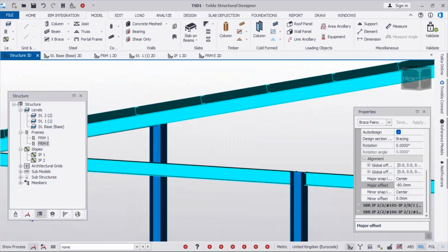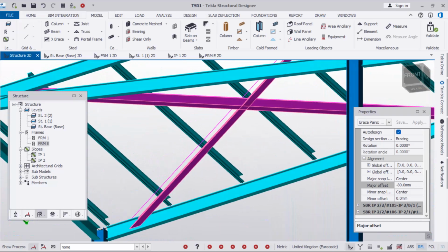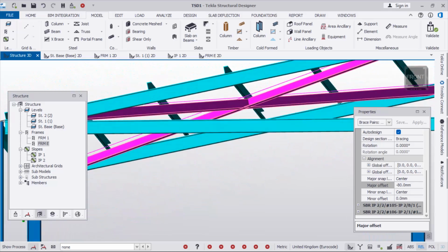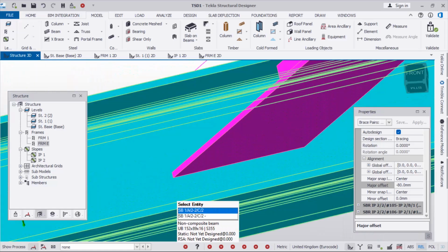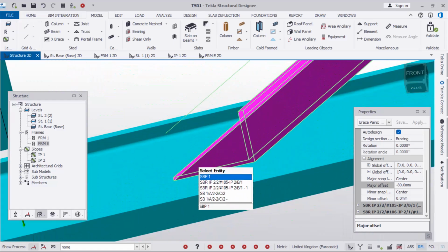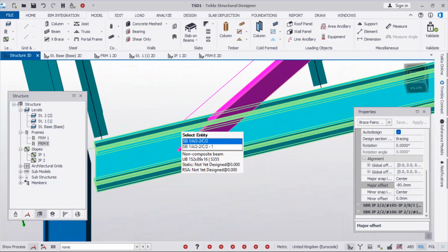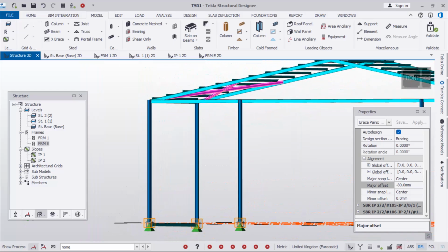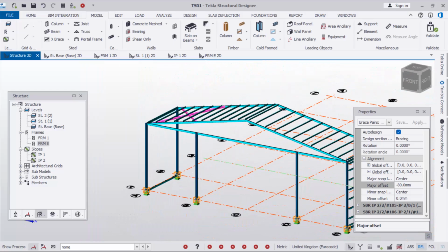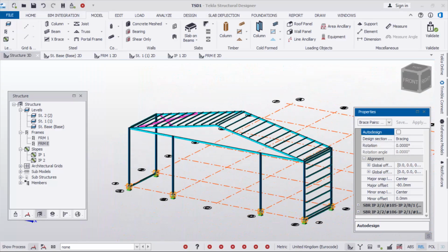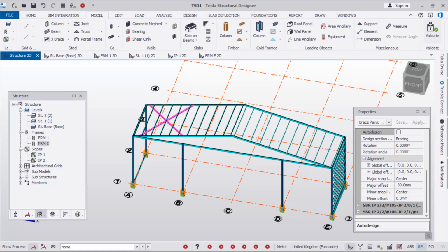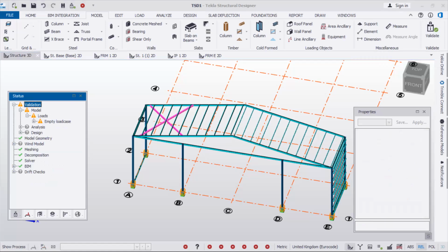All right, just like that. So that is going to snap at the web like that, just like this. You can see it perfectly. So it will be easy to do your connection here when you go to Tekla Structures, and then you can just tick here and check this. Then it's always good to validate your model, see if there's any error. You can see we don't have any error to do with modeling.